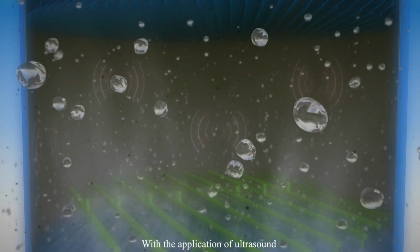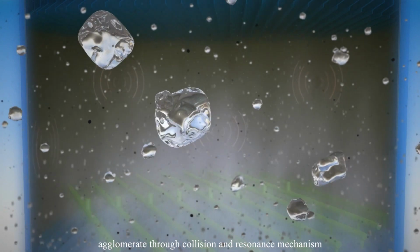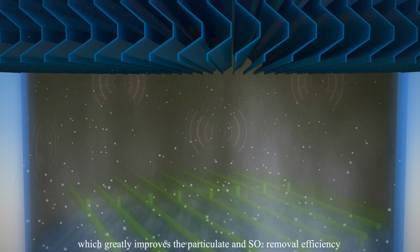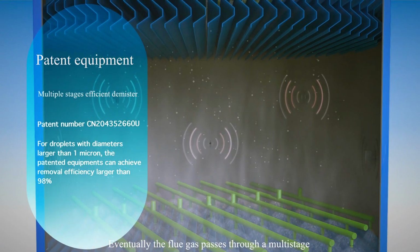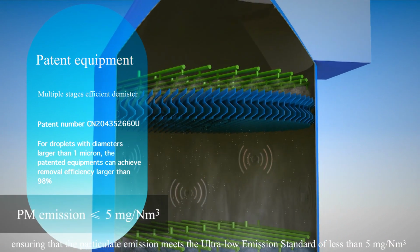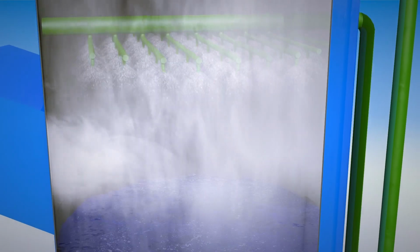With the application of ultrasound, the fine particulates such as dust and aerosol particulates agglomerate through collision and resonance mechanism, resulting in larger particulate diameters, which greatly improves the particulate and sulfur dioxide removal efficiency. Eventually, the flue gas passes through a multi-stage, patented high-efficiency demisting system, ensuring that the particulate emission meets the ultra-low emission standard of less than 5 mg per normal cubic meter.